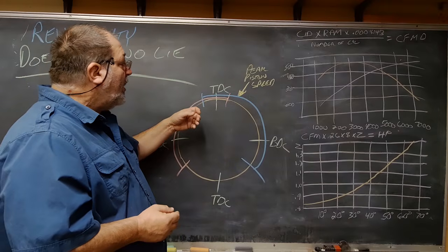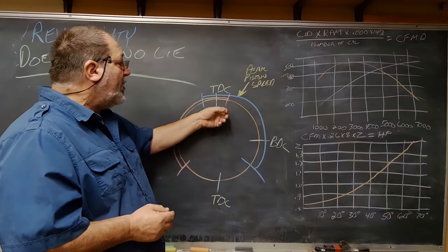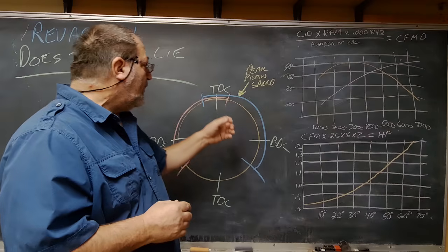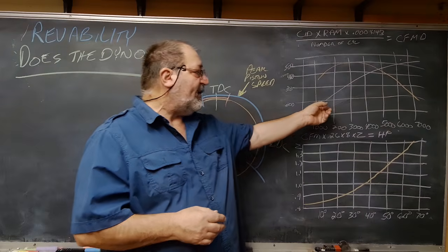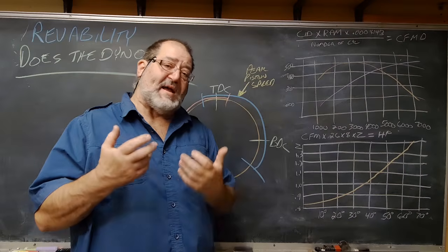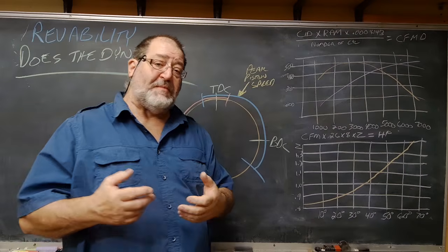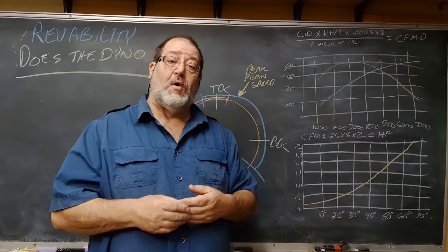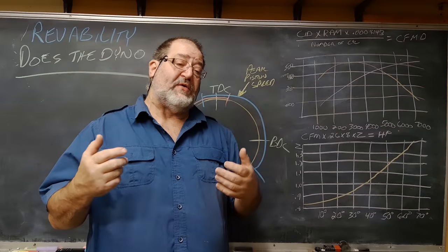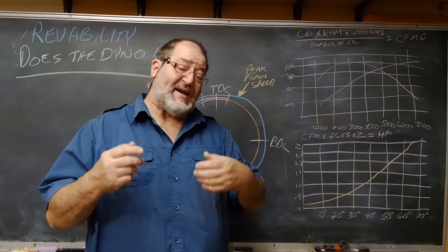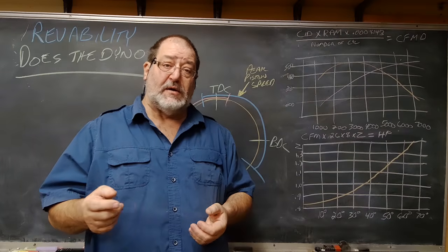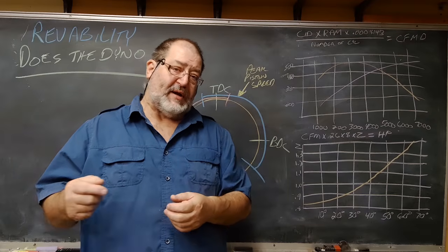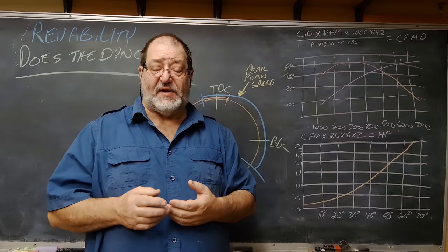And so, if you are limited in RPM, you may say, well, I'm going to run a smaller cam. I'm going to reduce that overlap so that my power down here is good. But that doesn't give you a good fill, and you can make a slug of a motor. A lot of my early ones back in the 80s, which is what coined this term, had that problem. I mean, you got to remember, we didn't have all the head choices we have today. So I didn't have the way high breathing ability of some of the heads that exist today.